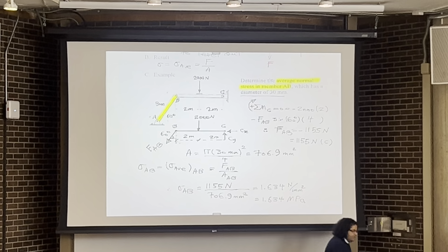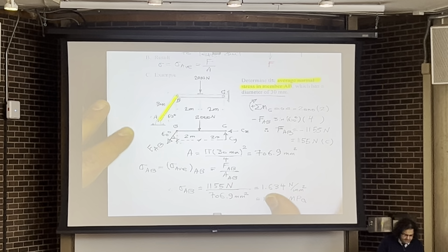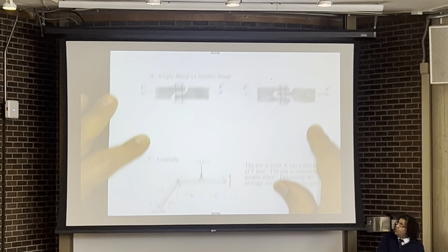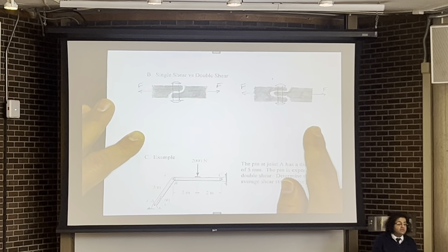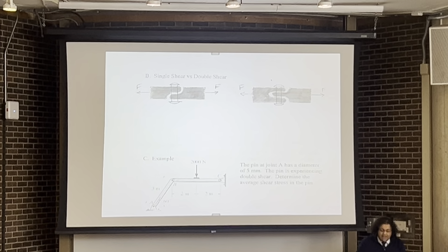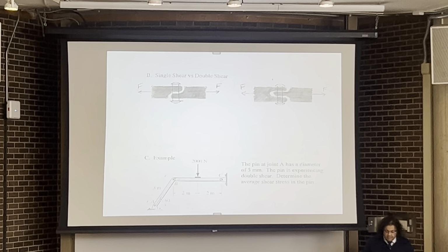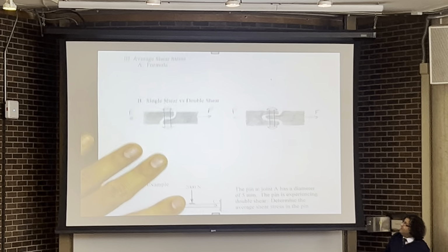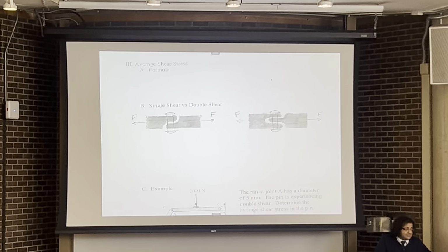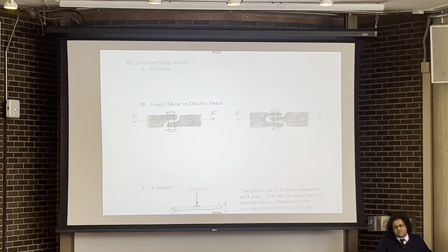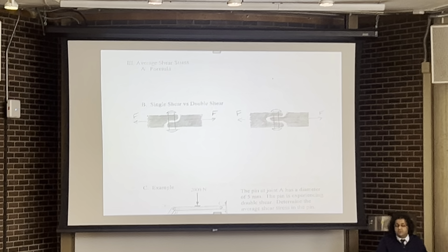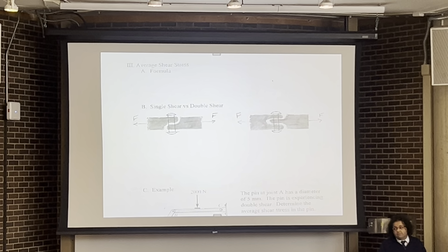So, if there are not any other questions, we can go ahead and talk about some examples where we can calculate the shear stress. Right now, I think you guys agree with me that we can simply calculate the stress as long as we can assume that the stress is distributed uniformly. So if the stress is distributed uniformly, we can just simply divide the force by area.